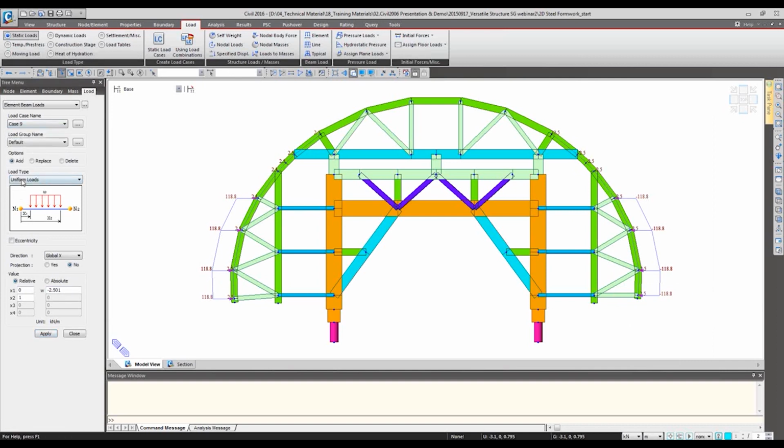And next, the second placement loading for the concrete in the lateral direction. So I can specify a different value for load case number 9, which is 180. Apply, and also for this part as well, I can enter the same value with the different direction. So just delete the minus value and apply.